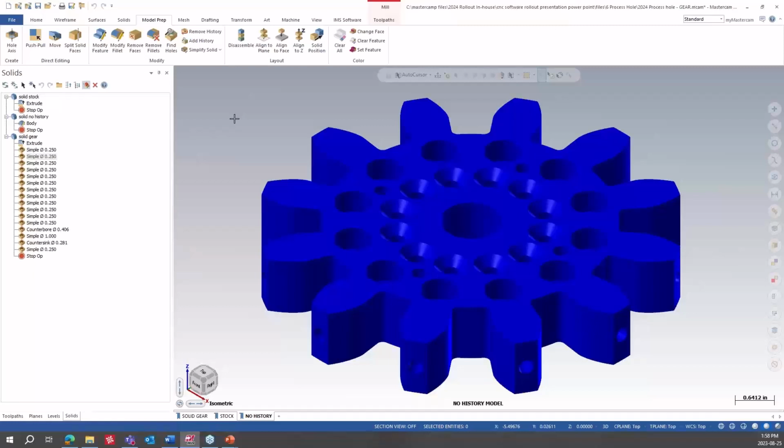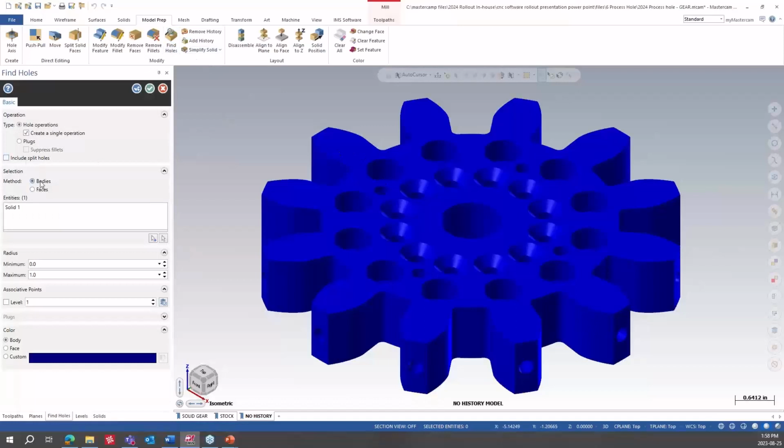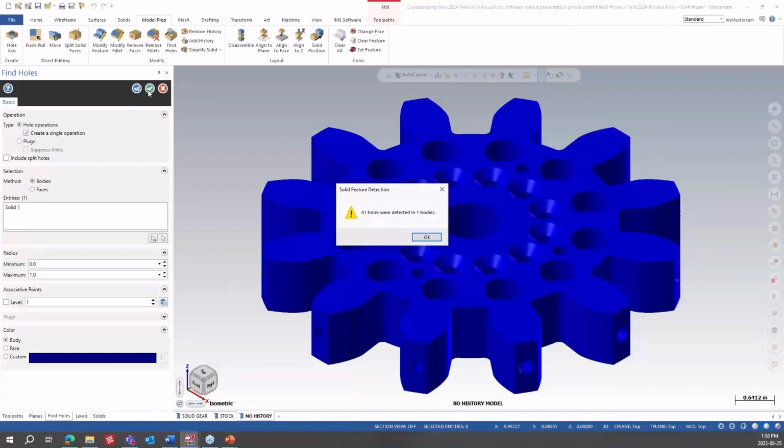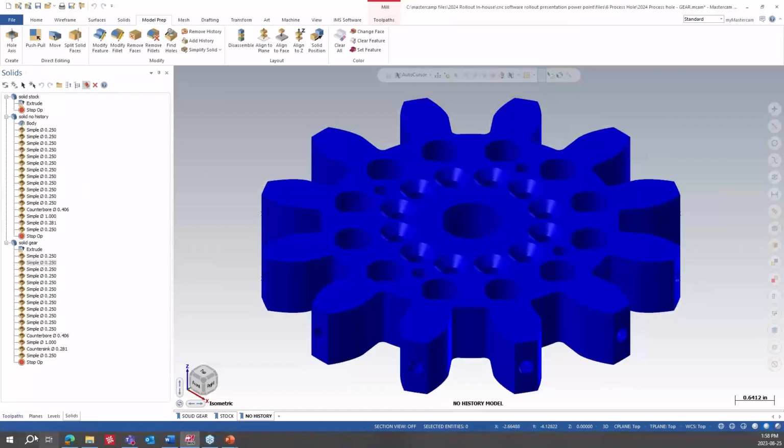Okay, just to be clear, we can use this on drill, circle mill, helix bore, chamfer drill, advanced drill, and thread mill. Those are the options that you have. So it's basically all your hole making toolpaths that this can be applied to. And as you mentioned, it is a work in progress, so with feedback, it will definitely be worked on and improved.